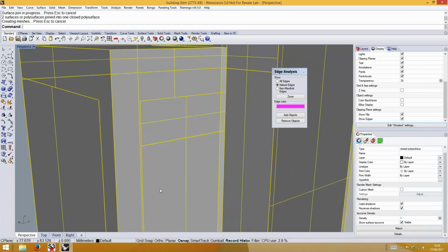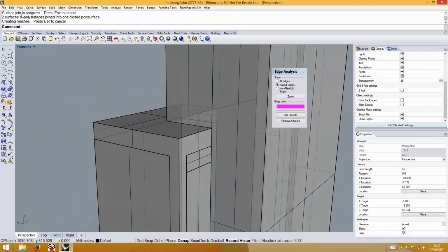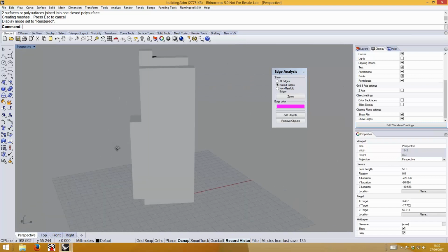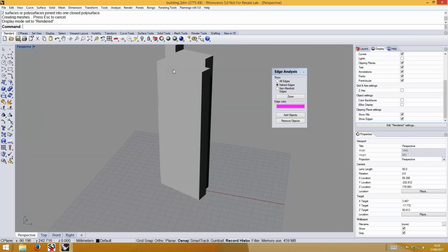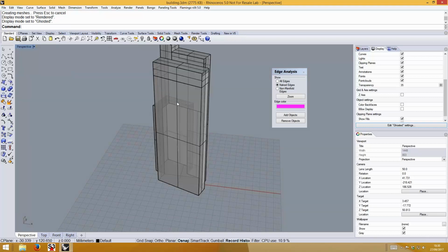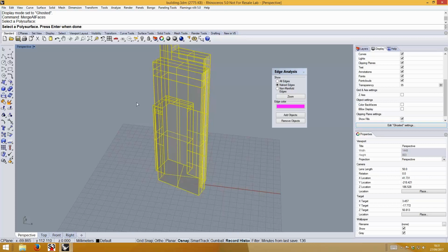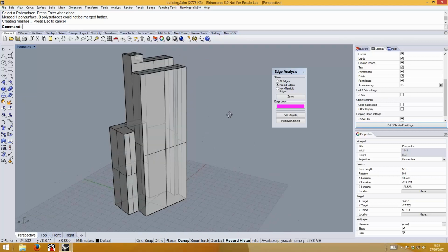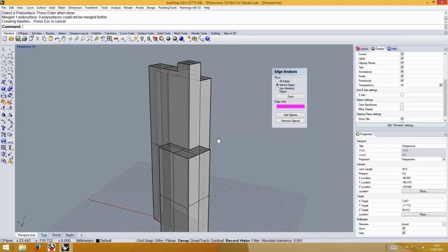Okay, this one looks quite okay, but still, I want to take a quick look here at rendered, and you will see that the model itself is actually quite easy, right? Even if this looks like a full single-face vertical surface, it's made out of many different patches. There's a command called merge all faces. Here it is, that will let you unify and merge all coplanar faces. So run it before exporting any file from Rhino, because it will let you reduce the number of surfaces in your geometry.